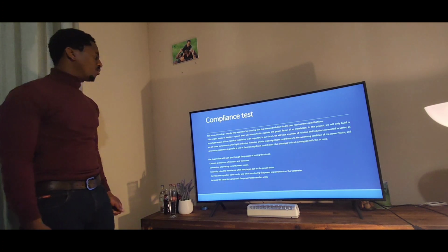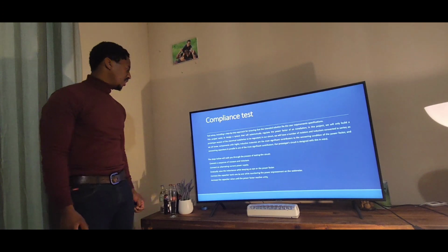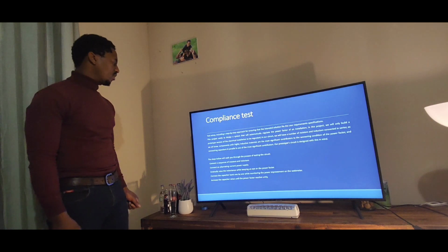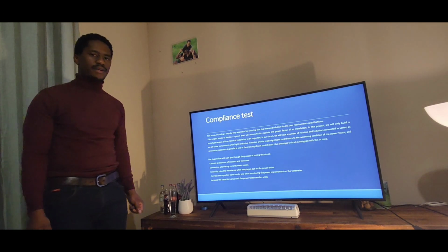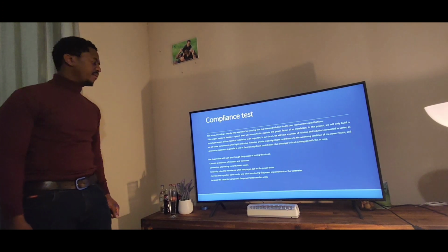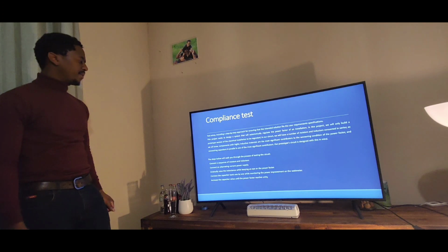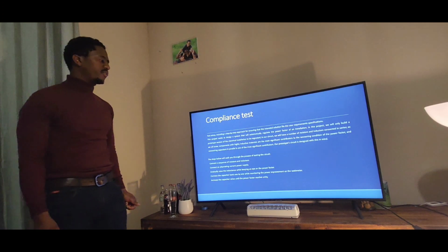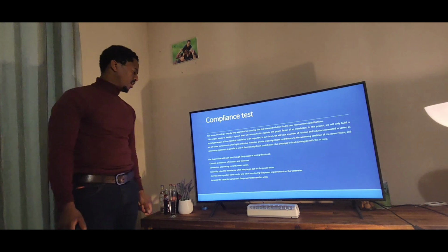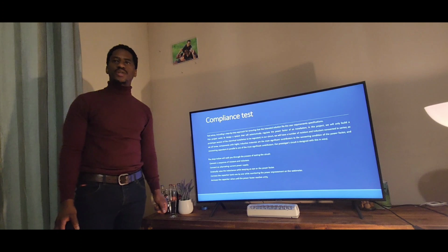The steps below will walk you through the process of testing our circuit. Connecting a sequence of resistors and inductors, connecting an alternating current supply, gradually increasing the inductive load while keeping an eye on the power factor, connecting the capacitor bank one by one while monitoring the power improvement on the watt meter, increasing the capacitor value until the power factor reaches unity.